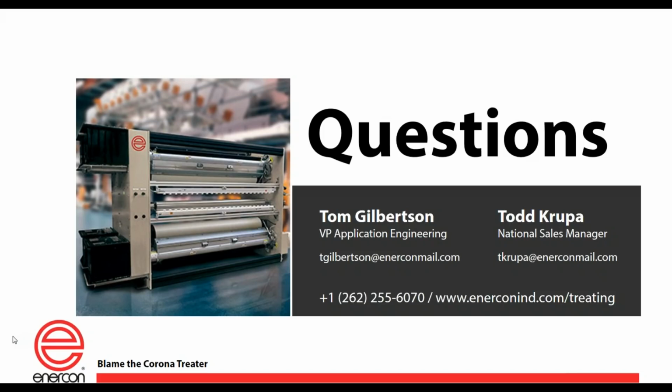Well, that's a great question. I've never had anybody ask me that question before. Let me just put it to you this way. If you have condensation, or you can actually see moisture on the treater roll, on the web, in the electrode assembly, things of that nature, or concurrently, if in that condition you're seeing the corona or getting high voltage arcing, where the treater's not staying on, it'll arc to that water, that would be way too much, right? So you want to make sure certainly nothing's visible.